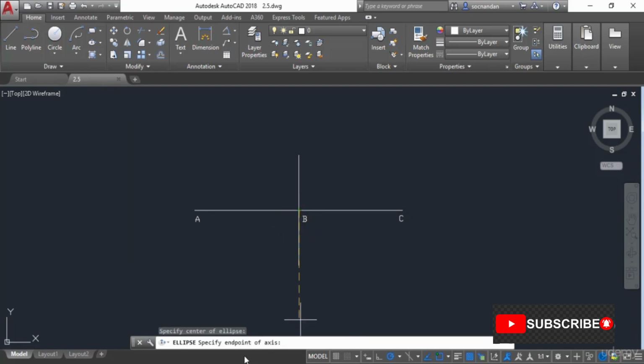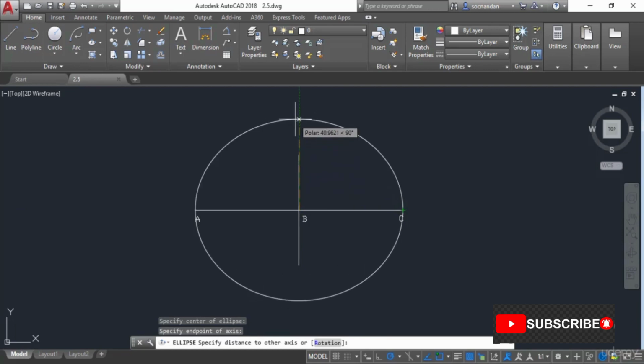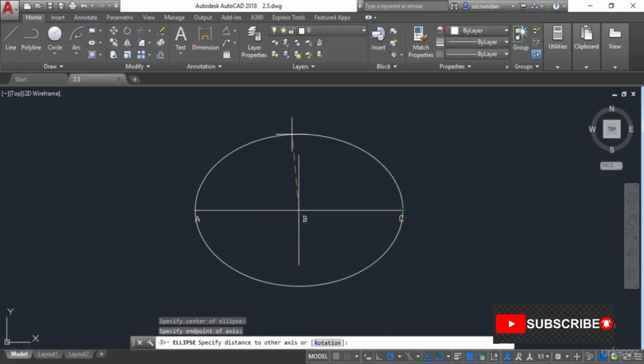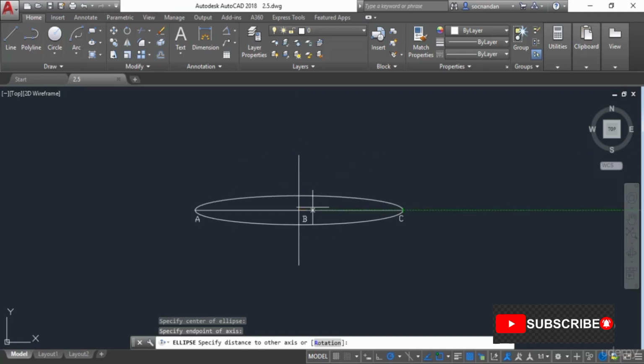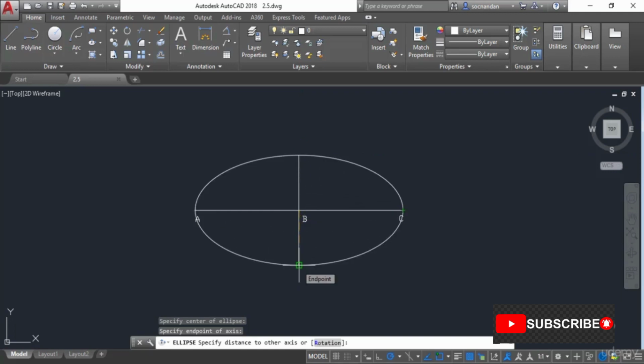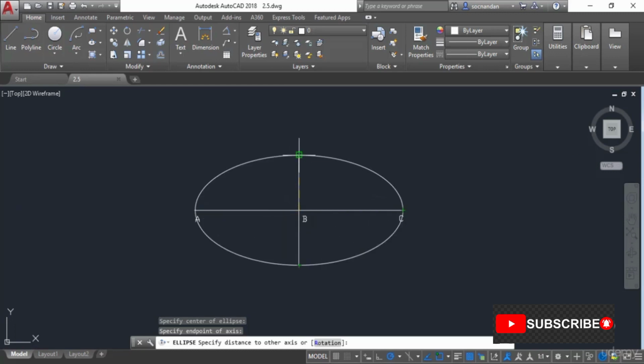Now we need to specify the end point of the ellipse, and we can take the end point as point C or point A. So let's take this point C as the end point of one of the axes. And now you'll notice that our ellipse is changing shape along with the cursor, and you can simply specify the next endpoint of the minor or major axis. So here we can specify the next endpoint of the axis as this point, or we can also specify this point as the axis endpoint. But first we'll click at this point here, and that will be the axis endpoint, and here we have it.